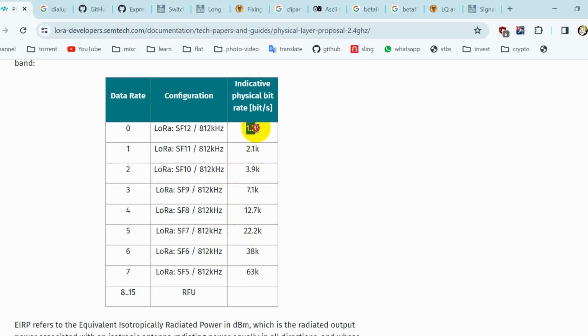And because this difference is about 60 times, what does it depend on? It depends on a coefficient, SF, the spreading factor. If we get back to the LoRa characteristics, we can see that the spreading factor is the setting that describes the form and the amount of these triangles.